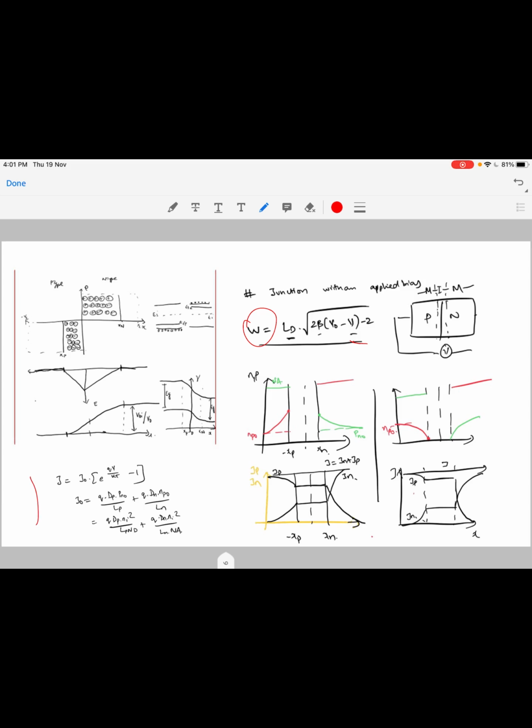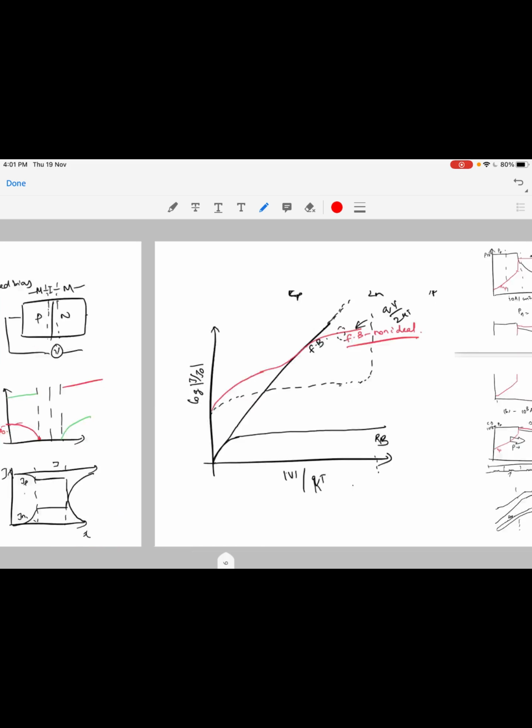And we derived the equation, which is called the Shockley equation, or the ideal diode equation, and we found the expression for the reverse saturation current to depend inversely on the doping density and on the semiconductor intrinsic carrier density.